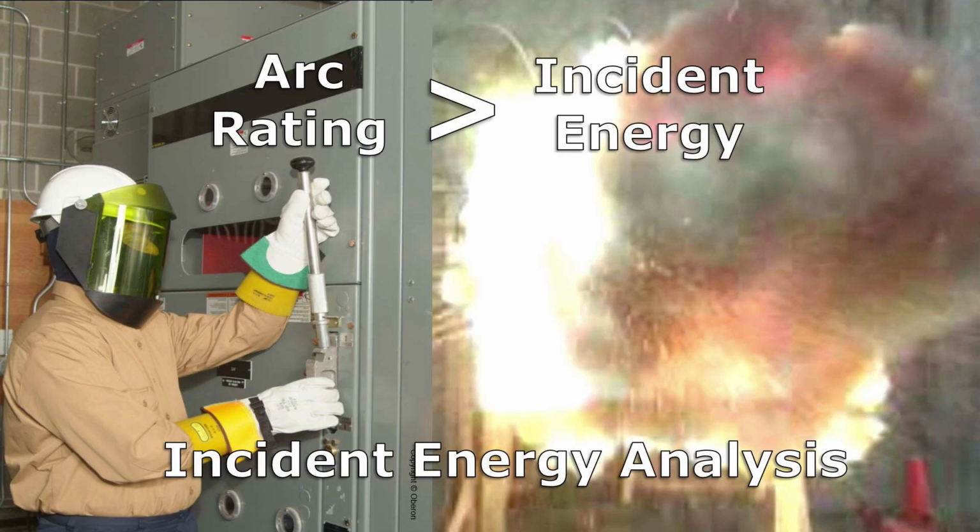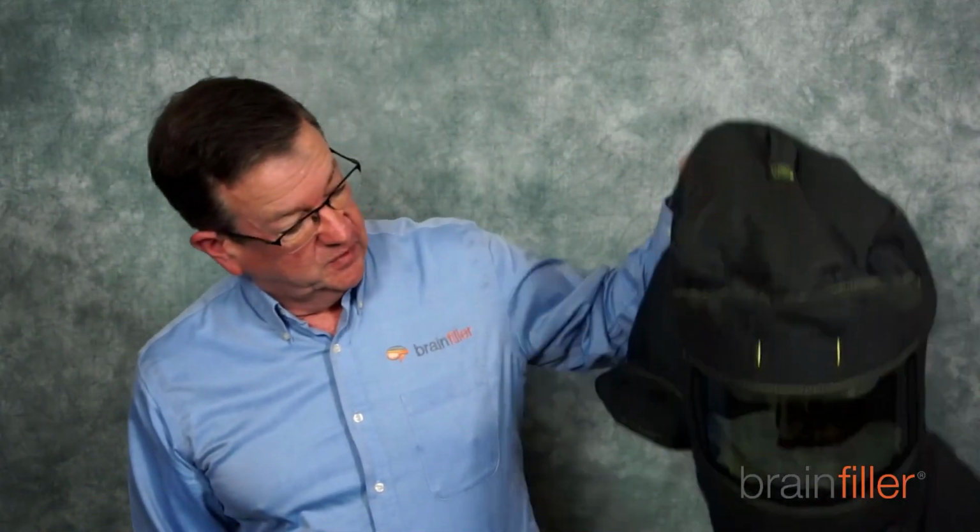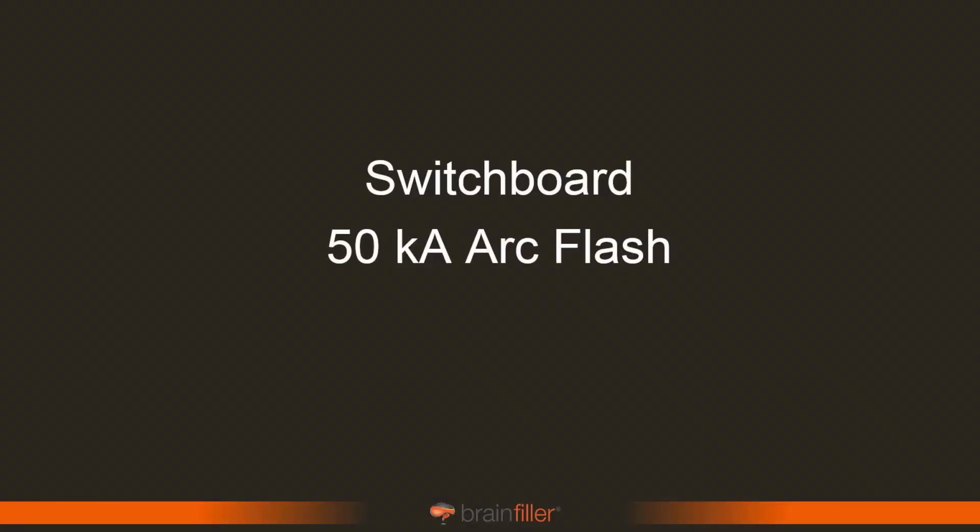An incident energy analysis. This is where you are selecting the arc rating of your protection to be sufficient for the incident energy. I sometimes oversimplify this, but I look at it in terms of, with the incident energy analysis, it's coming down to, are you going to be wearing the moon suit with the hood, or are you going to be wearing a face shield with a balaclava sock? And so really what an incident energy analysis is all about, all of the arc rated protection has what's called an arc rating, calories per square centimeter. And you want to select an arc rating that is sufficient for the prospective incident energy that could occur during an arc flash.